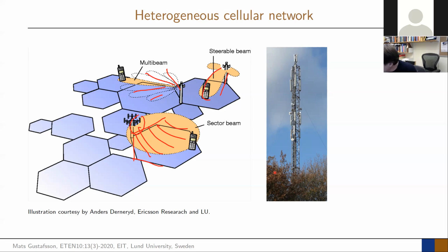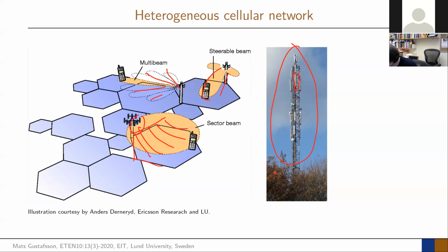So what we see here is on this base station, you see different types of antennas. We will see an enlarged photo of it very soon, but you can see in many cases some elongated objects here, and you can also see some round objects that sit here. So these rounder ones are typical dish antennas, which are microwave links between base stations. So they are typically not communicating to the users. They are communicating between base stations. And the elongated structures here are really the ones communicating to the user.